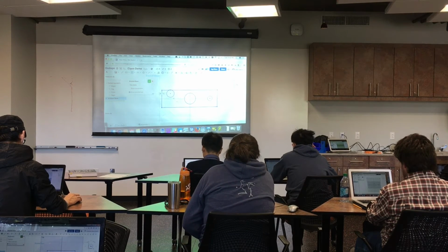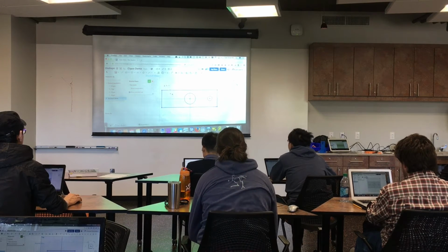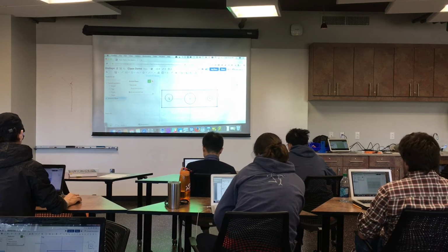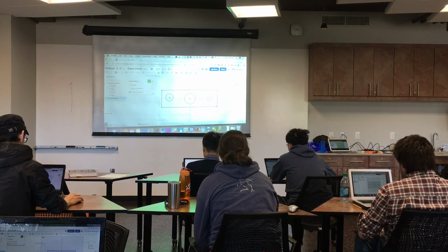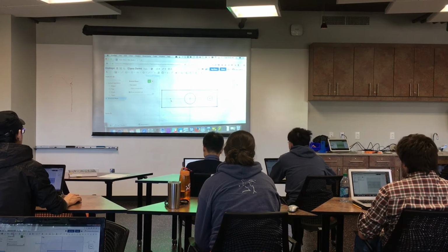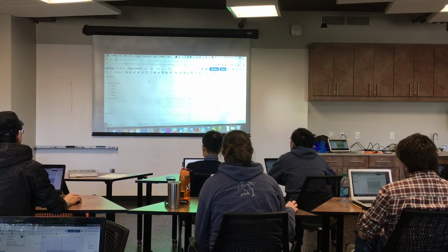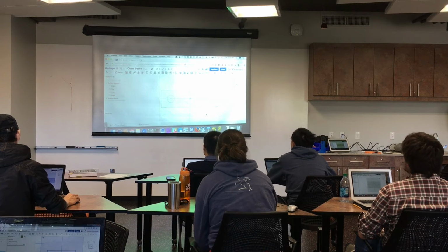All right, so let's say here, I'm going to hit escape so I get my pointer back. Here I screwed up. This circle can be anywhere. That's not what I want. I want it to be constrained to here. I can just hold it over there, and then let go. And now it should be constrained to lie along that axis. All right, so now we have a sketch. Go ahead for now and click the green check mark, which means I'm done working in this sketch, even though it looks pretty wonky and not like the part we want.